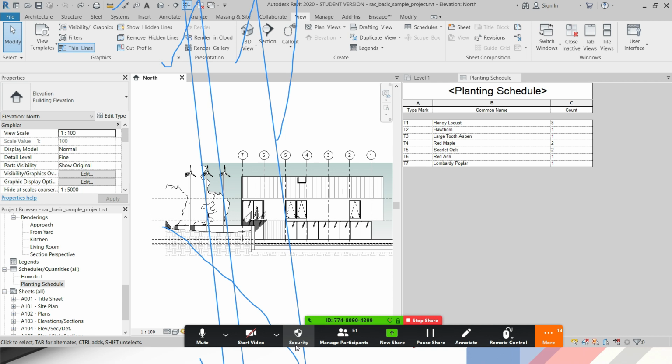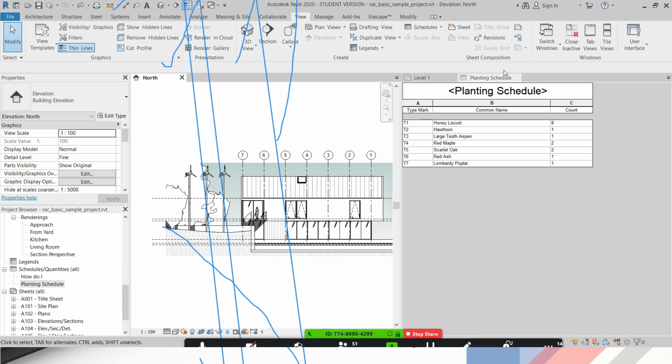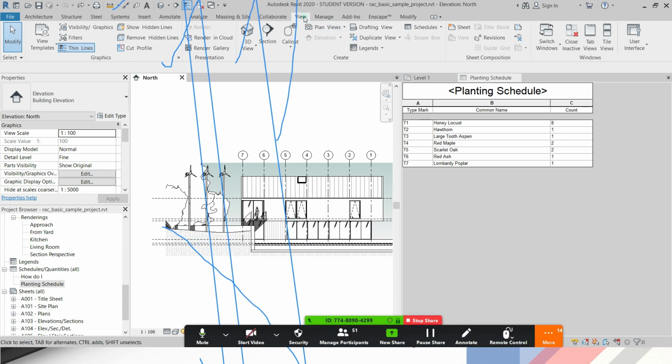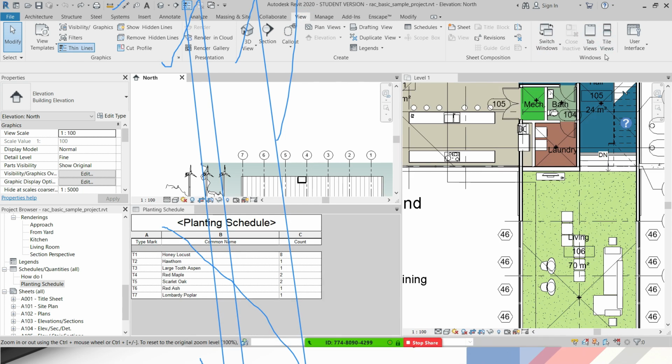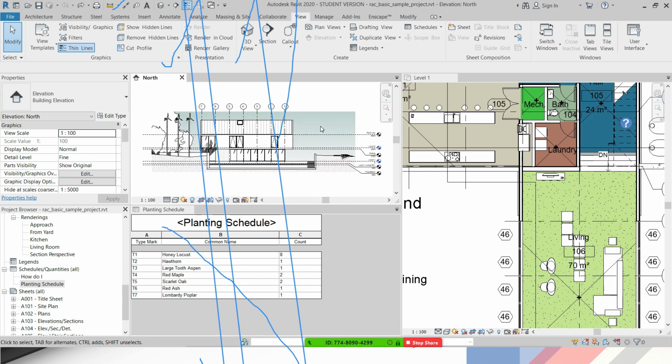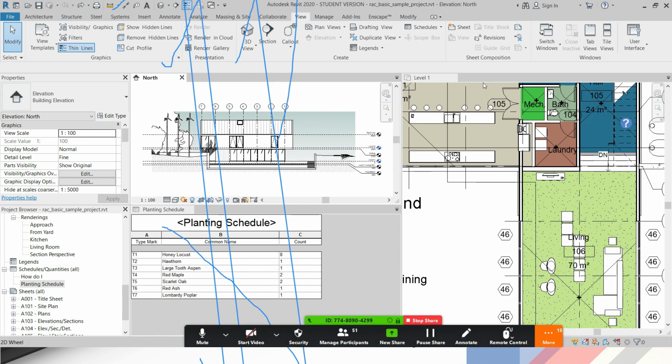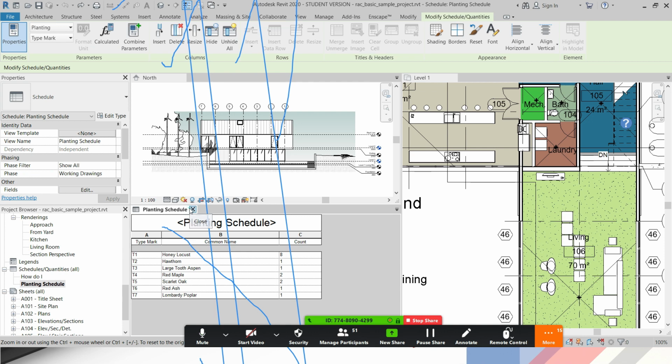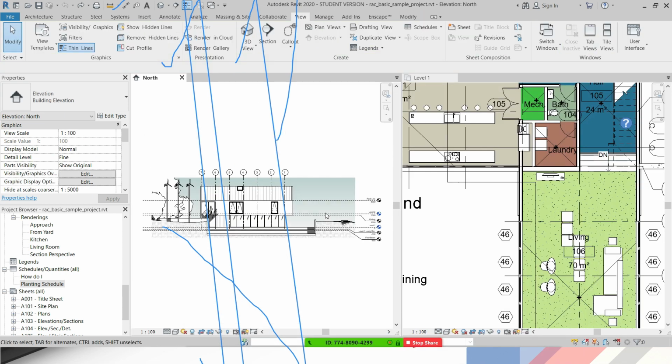What was that you said to have a view of elevation as well as a floor plan in one screen? What was the option? The option is from View, you can select Tile Views. Tile Views, yes. There is a shortcut for this as well, WT. Okay.